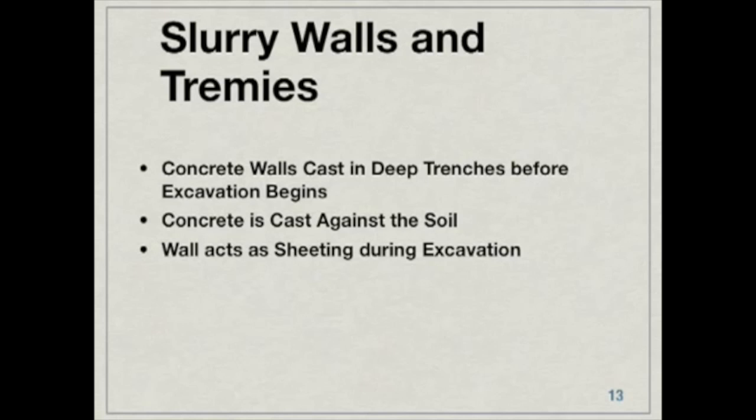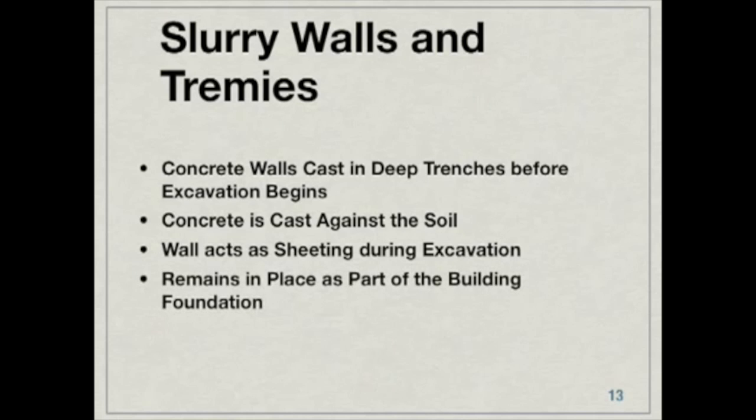Now, obviously, as we're filling this trench with bentonite slurry, we are trying to also get the soil out. So we have special excavation equipment called a modified clamshell used to extract the material through the slurry. After the excavation for the entire primary panel is complete, a reinforcement cage is then lowered down into the trench. Concrete is placed in the trench panel using usually 2 or more Tremie pipes.